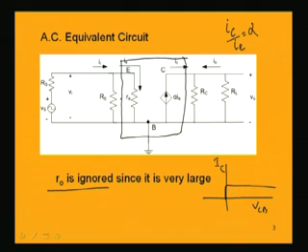and we were having almost horizontal characteristic curves in the output characteristic, that is, without any slope. So, even though we change VCB, there is not going to be any change in the collector current. That is why we can very well assume that this resistance, which is actually present in the output of the transistor, that is, the output characteristics will give us the output resistance, but that is very large, almost equal to infinity.